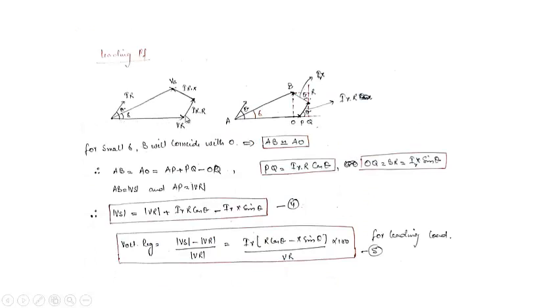So the voltage drop IR into R in this case will be added, which will be in phase with this IR, and then a voltage phasor IR into X, which will be perpendicular to this voltage phasor, in this direction. Then the net voltage, that is V1, or here it is Vs, will be obtained by connecting this point to the tip of this phasor. So this will be equal to V1. I have redrawn the same figure. This voltage phasor up to this P will be V2. This will be V1, this will be V2. So this will be delta.